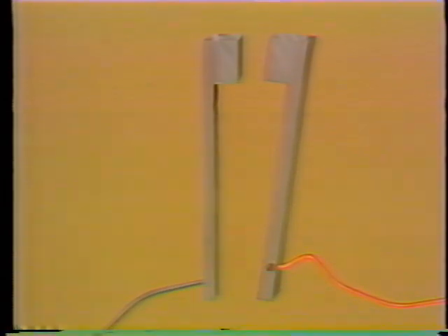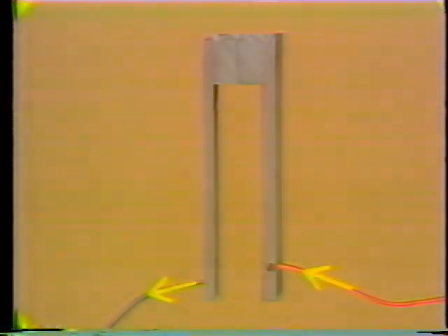This switch is part of a circuit. As long as the switch is closed, current can flow through it. Opening the switch interrupts the current flow, as you know, but let's see what else happens. A switch opens very fast, but we're slowing it down so that we can see what occurs. As the contact points separate, air becomes part of the circuit and heats up. When the distance is very small, the air is very hot. In fact, the air is hot enough to conduct current, so an arc is formed between the contact points of the switch. As the switch opens wider, the arc gets longer.